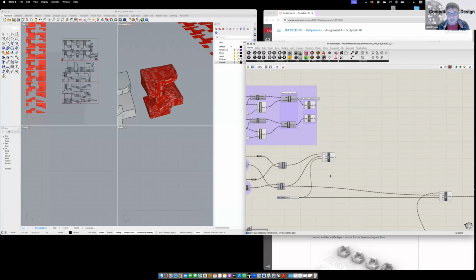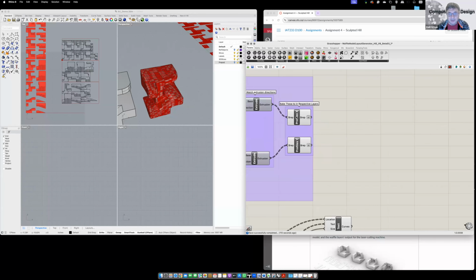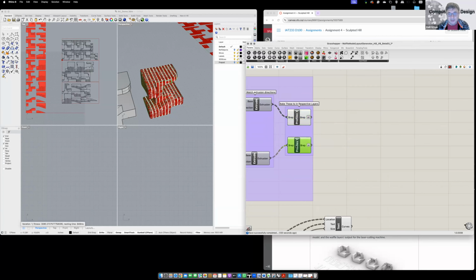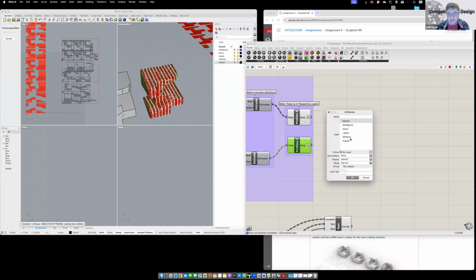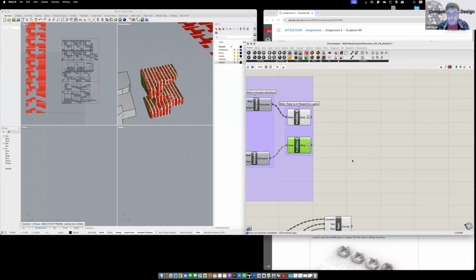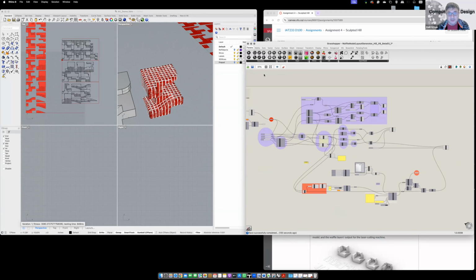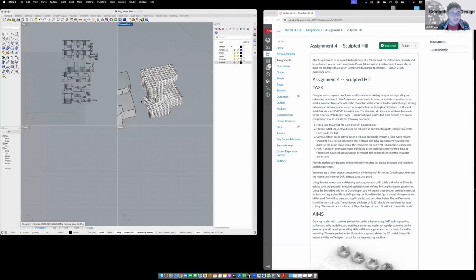And then I will bake this profile. Bake. Now this is 3D slice. I'll put it here. And Y. Bake. This is 3D slices. I am done with this in Rhino. I'm going to save this. The version that I'm going to share with you is called 0.3.1. Let's close this and see what we have here.